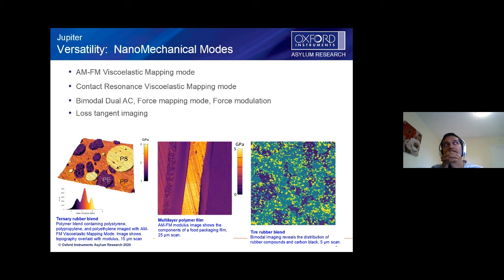You may want to write this down. The probe is called FS1500. It stands for Fast Scanning 1500. FS1500 would be a nice probe for this measurement. And I would perform this measurement in tapping mode and make sure your parameters are set up so that you are applying a very small force between the tip and the sample, because PDMS is very soft.